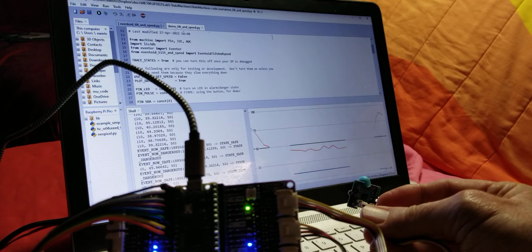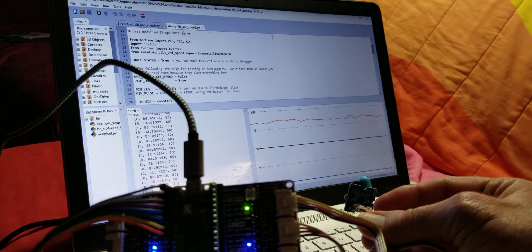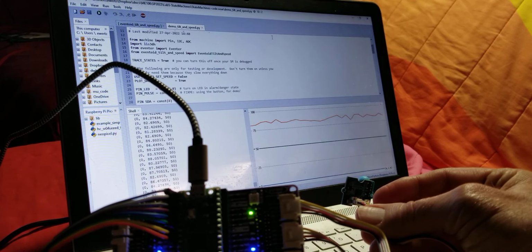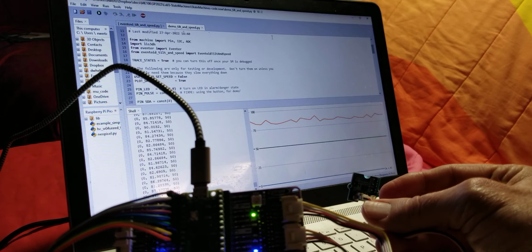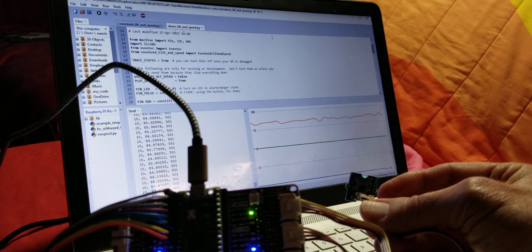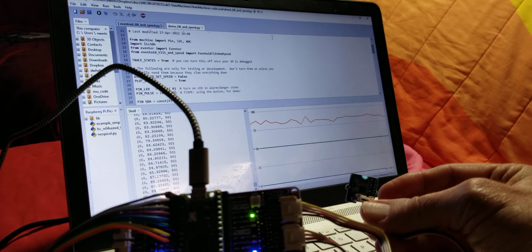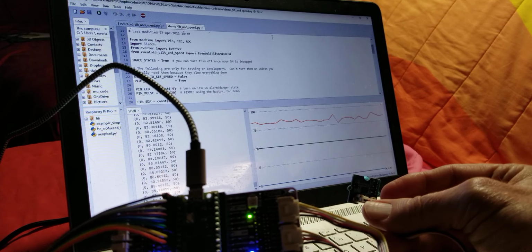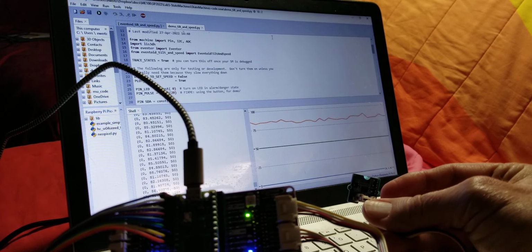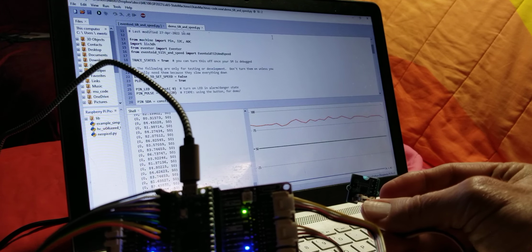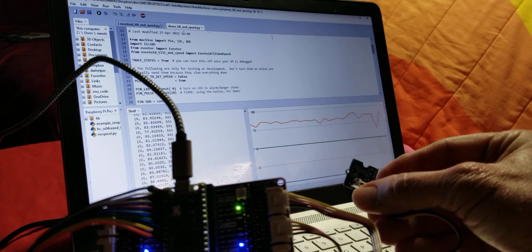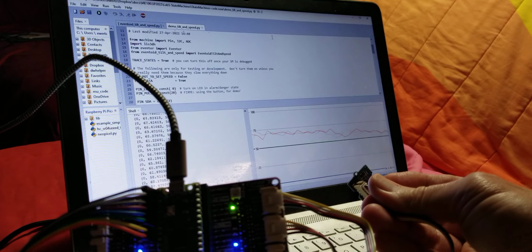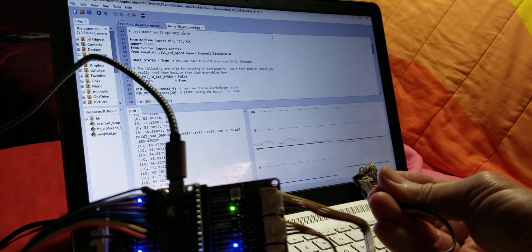unsafe, safe. And because all comparisons like this kind of need some hysteresis, you'll see in the code that there's a hysteresis band of like 10%. So as long as the speed is 90% of the tilt, it is safe, in a safe operating range. And if it's above like 110% of the safe operating range, then that's an error. Otherwise, if these two values were to get close to each other, you'd see a huge number of events get generated, and that's basically useless for a state machine implementation.